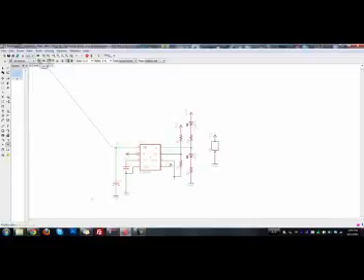I like to choose this little tag thing, which I think looks a little bit nicer. And you can rotate it by clicking one of these buttons and just stick it right there. So now this was already called $9, but now we're just able to visualize it. And I'm going to add a similar tag over here by clicking on this guy and adding the same tag. Now these are not connected right now because this is $9 and this is $5. We want to make them the same.